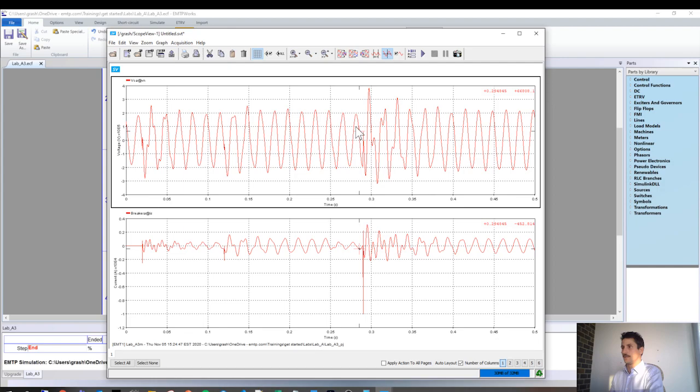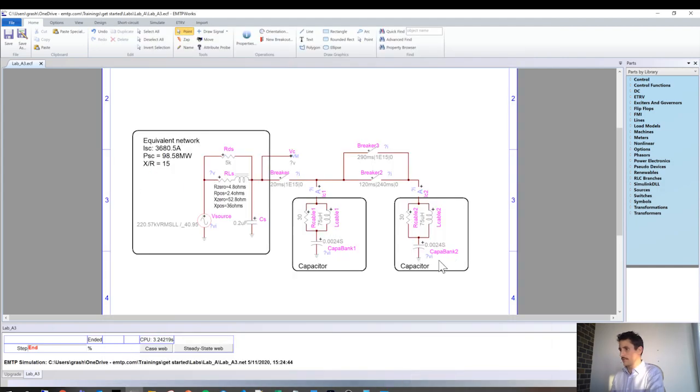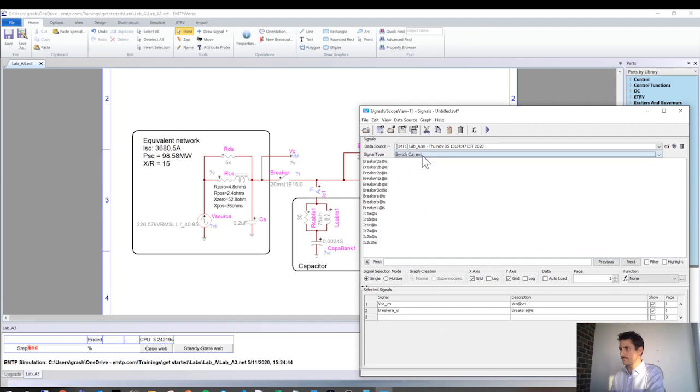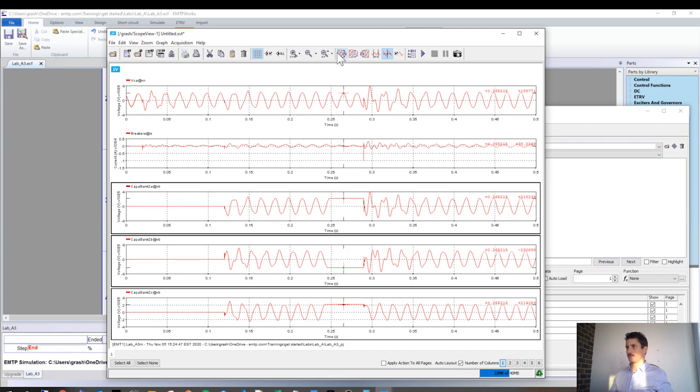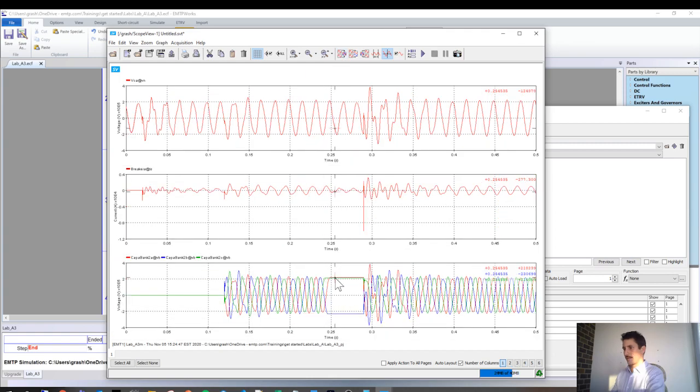And then, I don't know if we can see, let's take a look at the voltage here in cap bank 2. Okay, perfect. So we see when we disconnect the cap bank, 1 per unit is stored approximately. And then when we reclose, we have much higher overvoltage than before, much higher current. And so in this case, we don't simulate next week's restrikes, but it's really possible you have more and more restrikes and the voltage escalation. This can be simulated, by the way, if you use the breaker in EMTP and enable the restrike option. You can simulate that and visualize the voltage escalation.